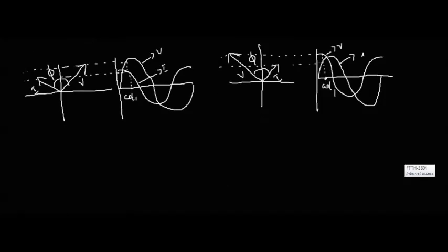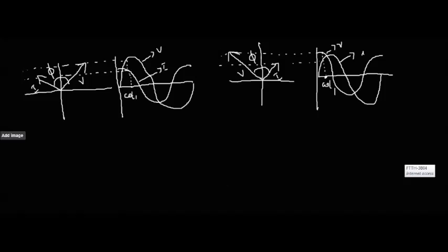What will happen if in a series LCR circuit the value of Xc is equal to XL? If Xc is equal to XL, the circuit will behave just like a pure resistive circuit, so the phasor diagram will look like that of a pure resistive circuit.